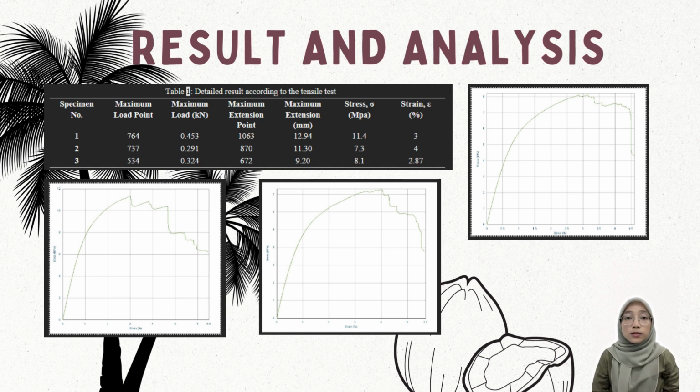Meanwhile, plate 2 exhibited the lowest tensile strength and load-bearing capacity among the tested plates. This outcome could be attributed to the bonding quality between the coconut fiber and the matrix, which was carpenter glue. It is possible that the matrix did not fully utilize its supportive role for the coconut fiber due to changes in the liquidity or elasticity of the matrix over time.